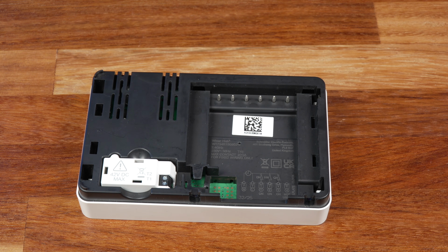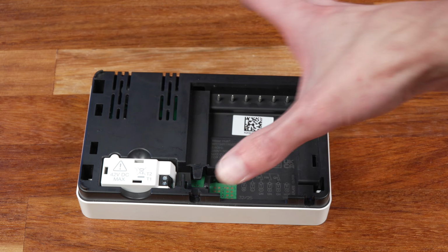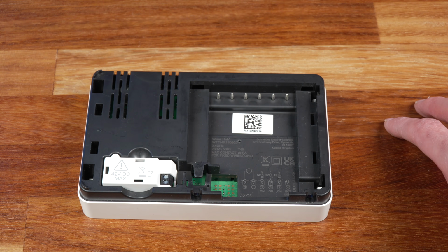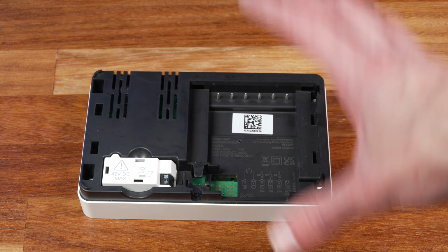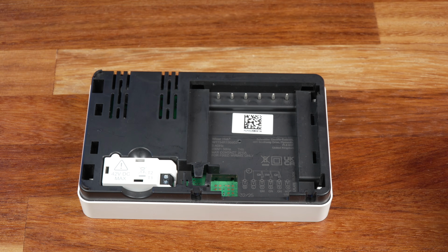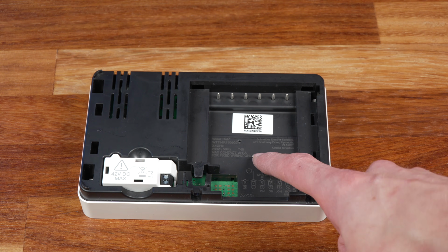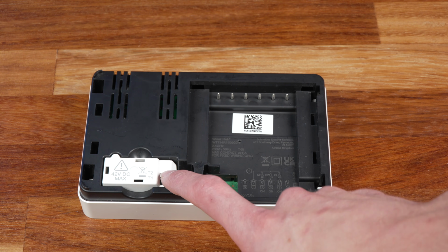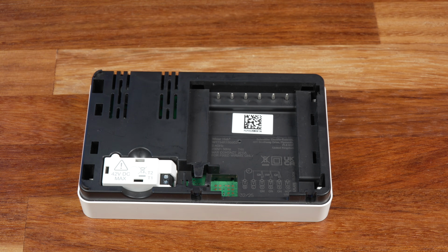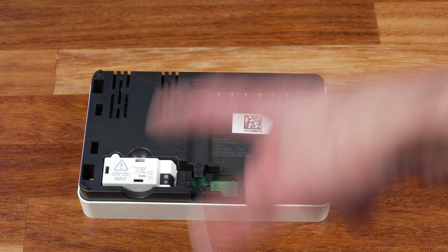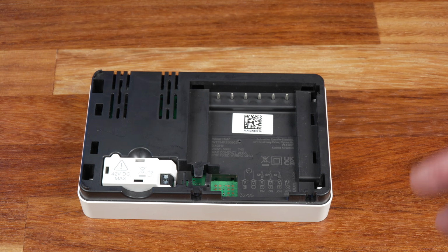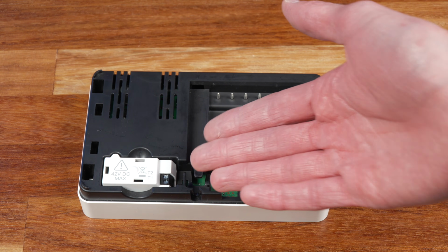and it also runs a lot more efficiently. As I mentioned, we'll be doing a dedicated video on this talking about OpenTherm, but with Wiser it gets a bit weird and vague because they officially state that the single zone 1-channel hub with a combi boiler fully supports OpenTherm. But then the 2-channel and 3-channel hubs like this also contain the OpenTherm module, although there's part of the manual that states that it's only supported on the 1-channel hub, even though this supports it. They even say in a couple of places where it's not supported even if the module's present on a 2 or 3-channel hub, but then other places selling these list the 2 and 3-channel hub as supporting OpenTherm.